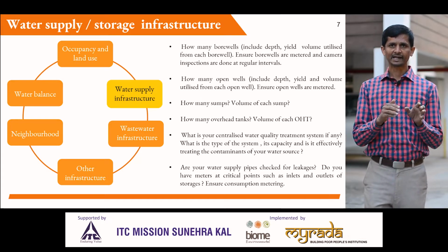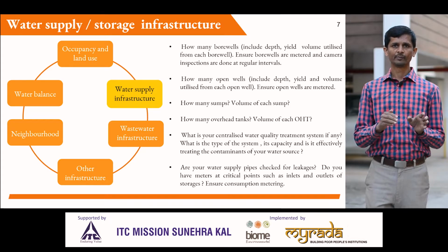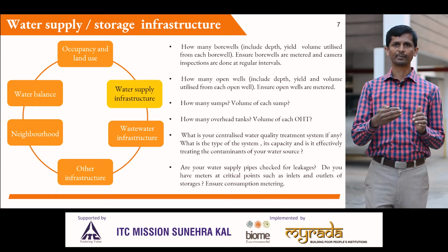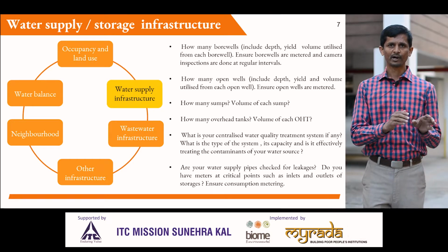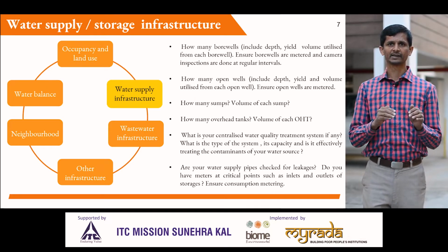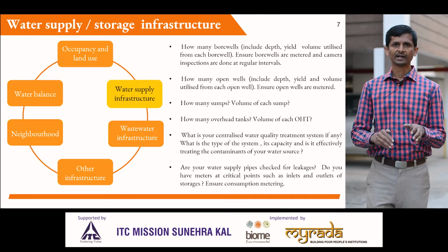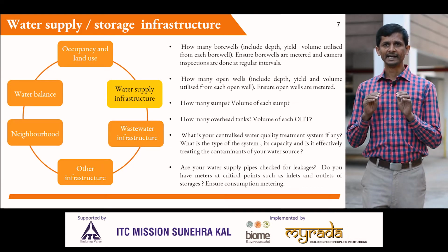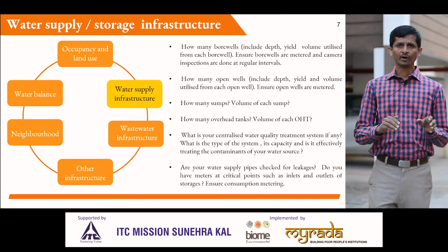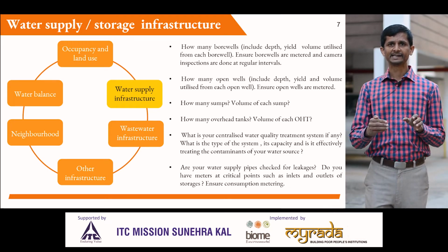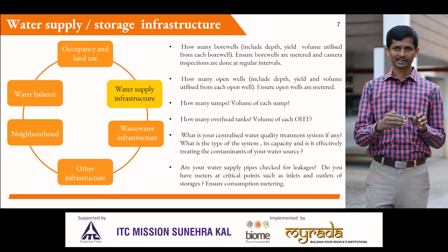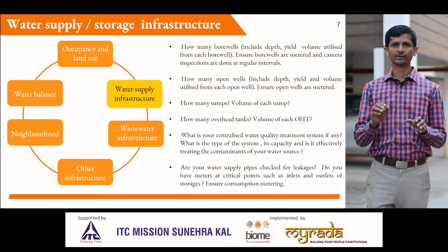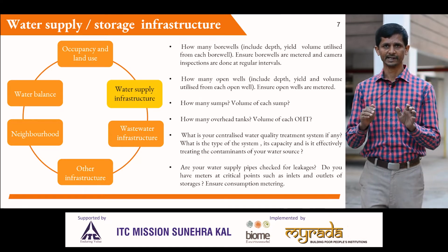Is metering done at source like bore wells, open wells, municipal supply to know how much each source is supplying? And at critical points such as inlets and outlets of storages, and consumption metering to know the exact end usage of water. Also identify if there are any leakages in the storage structure and in supply pipes, which is essential to know what the real consumption is.